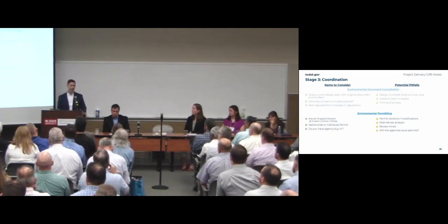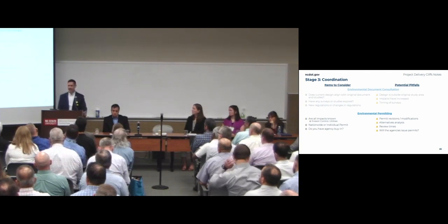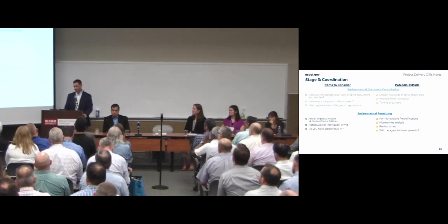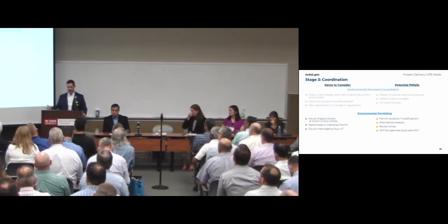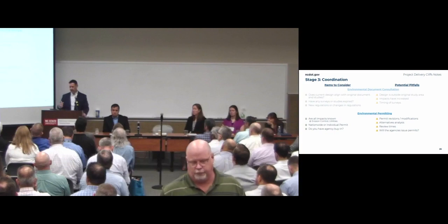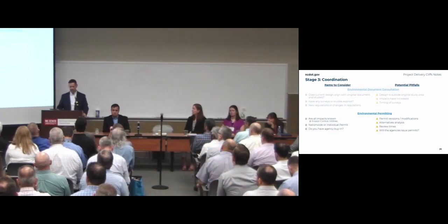Some of you may have dealt with this issue with a 2-lane median divided typical section. The agencies don't like those at crossings if you can't justify that median. So we ended up having to go back, coordinate routinely with the Corps, do some design revisions to reduce that typical section at the crossing. So just a lot of things can occur throughout a project. So communicate often with those agencies and make sure they're on board with what you're doing.